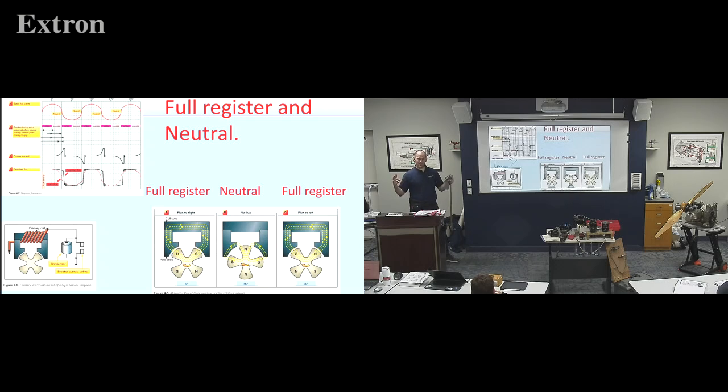We had electricity going through, and we open the switch and say, not anymore, sucker. And that sudden stop of amp flow makes that field collapse. The collapsing field collapses across the secondary, making a huge voltage, and we get one spark.